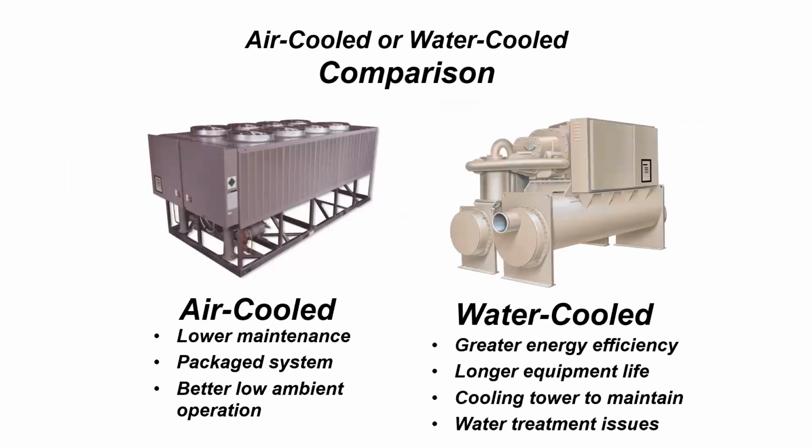Air-cooled chillers are really great in terms of low maintenance. They're closed loop, with no problem in really cold ambient winter conditions. They're packaged systems, so they use much less volume. They can be located on the floor. And they work great in low ambient conditions. So if there is a climate that is not too hot, those are really practical.